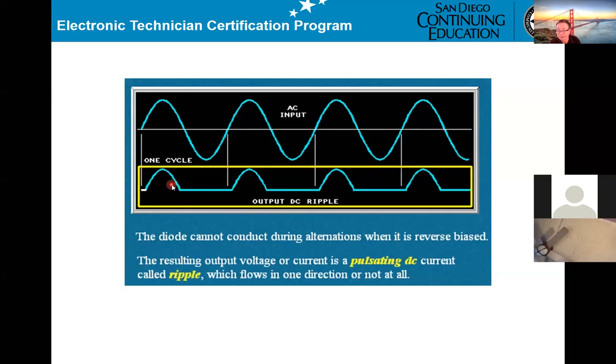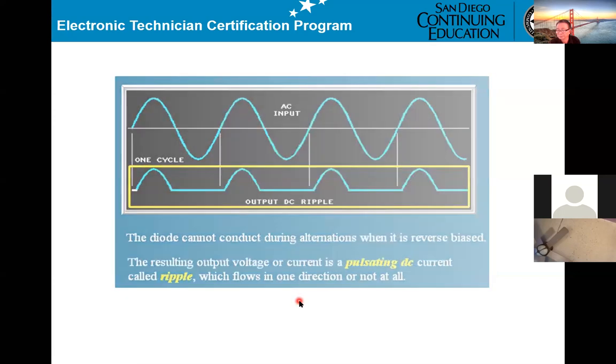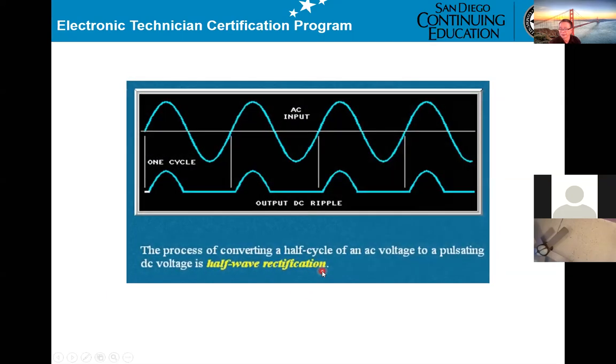The current is going left to the right. Zero here, no current. And right here, the same direction, left to the right. So that's why it is DC. However, that one they call pulsating DC, not completely DC. And that's why they call it half-wave rectification.